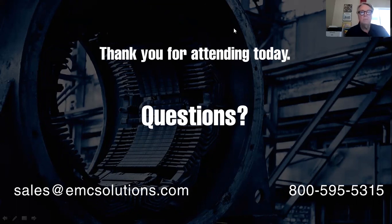Now, EMC, TCI, MTE, Mirus, all these people make filters that are pretty similar. The nice thing about the EMC filters for me is that we generally package them with the drive. So instead of getting 2 boxes that you have to mount and wire between and then hope you get everything wired right, at EMC, we generally like to put that filter in the drive cabinet with the drive and test it all at the factory before it leaves the factory. So you've only got one enclosure.